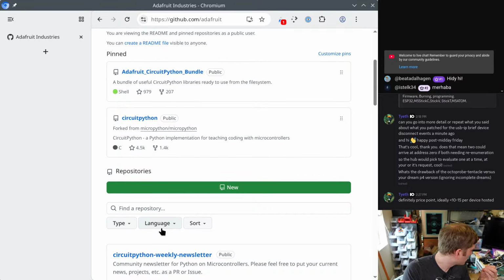And then you want a bunch of GPIO pins out, and then you want an adapter to a particular form factor. Because most of what I'm doing is testing certain dev kits, right? So I could have an adapter between this board with a lot of pins and a QT Py, and this board with a lot of pins and a feather, and whatever form factor I'm wanting to test.